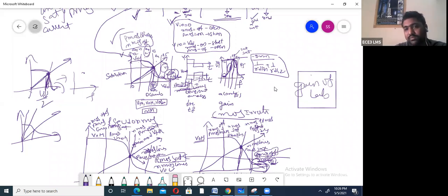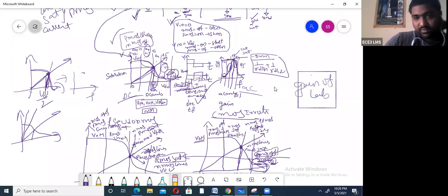Transient analysis you already know, you did it in the lab. I think in the Mentor Graphics lab, you are not doing DC analysis and AC analysis. Actually, these three analyses you have to do for inverter design. For amplification designs, you have to do DC analysis and AC analysis. For digital design, we go only for transient analysis, because we are just checking whether the circuit is operating according to the design or not.